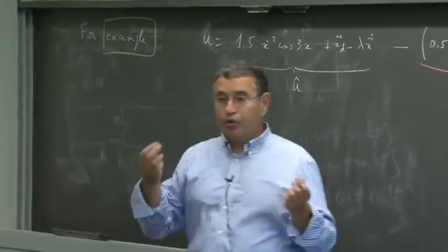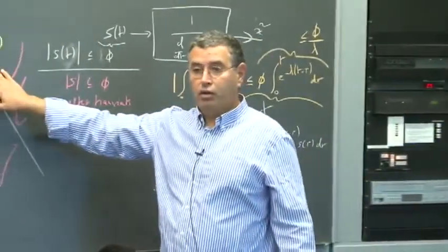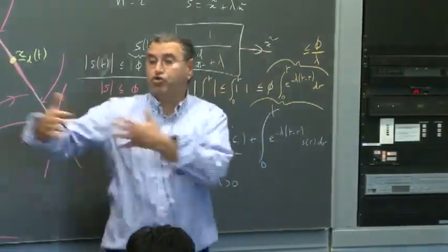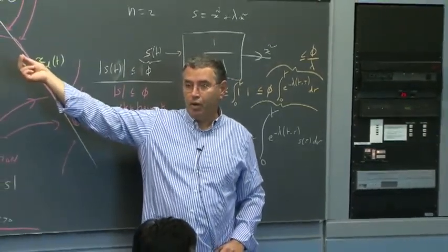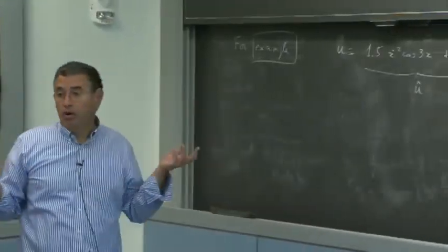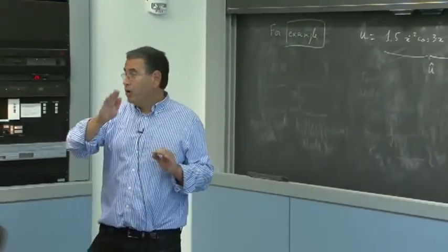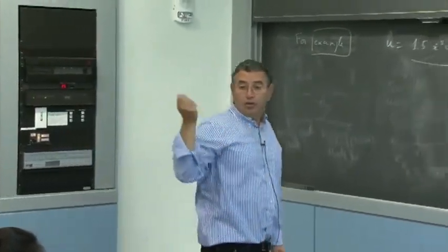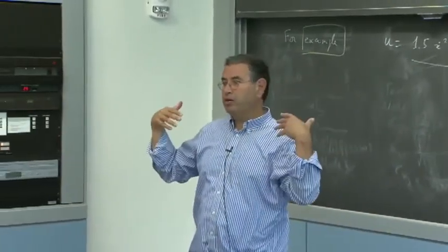And in particular, suppose for instance we start at x equal xd. So we give, if you want, the system a feasible trajectory to follow, because a physical system is not going to jump. So if you start exactly at x equal xd, what happens? Well, you keep verifying this equation s equals 0 with initial condition 0, so you stay at x equal xd. So if you start at x of t equal xd of t, remember xd is a trajectory, you keep following this desired trajectory exactly, regardless of the uncertainty outside.